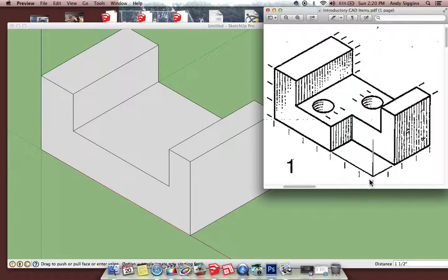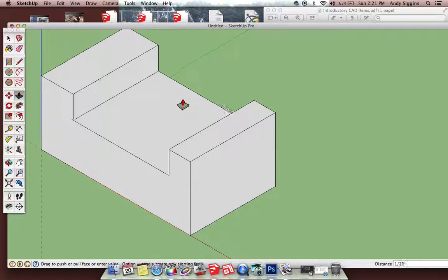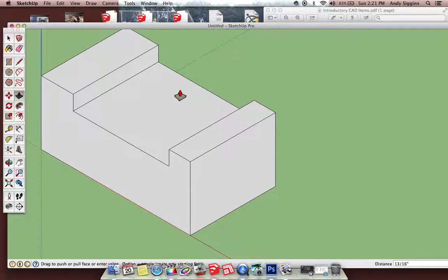So in this case, I know 1, 2, 3 inches in, I have this surface, and then it's being pushed back 1.5 units back along the y-axis. You can also see that it's 1.5 because there's half-inch increments identified here from which this edge also lines up with. So 1.5, well, roughly 1.5 over here. There's no solid indication of that, and an additional 1.5 marked over here, just to make sure you're creating this to the proper size.